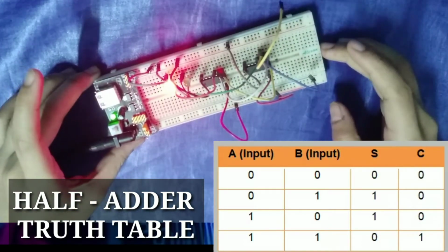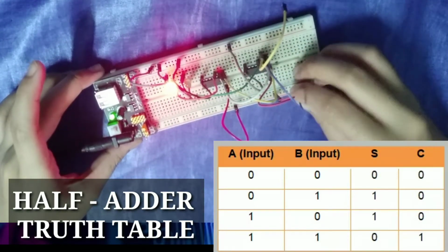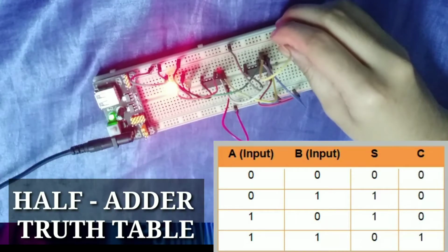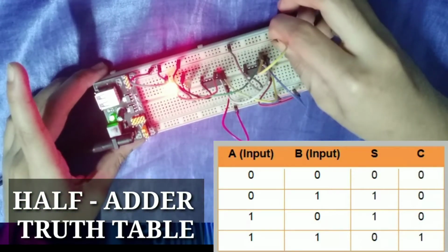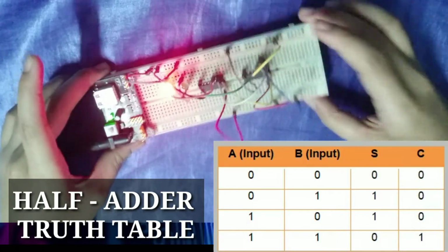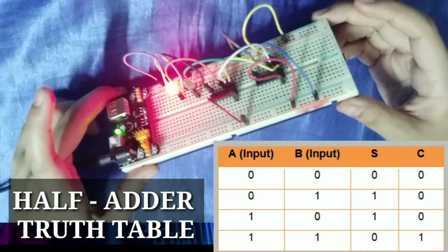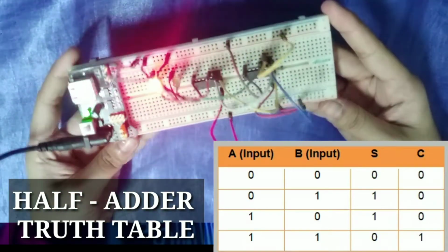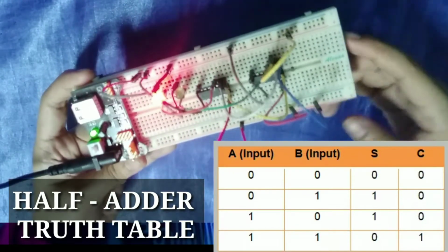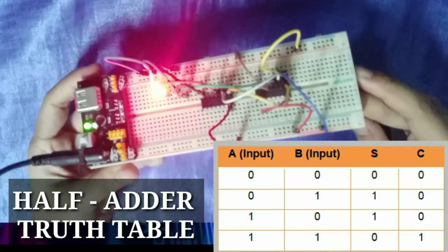Lastly, if both of our X and Y inputs are connected to our VCC, or all of the inputs are 1, as you can see, the output for our carry bit lights up. So that's the red LED here, which is our carry output. So that's our output for our truth table, namely the half adder circuit.